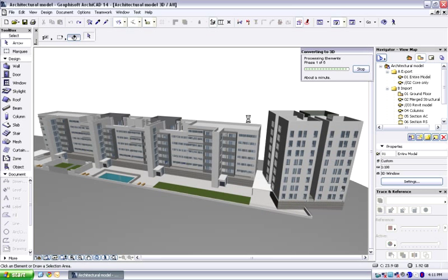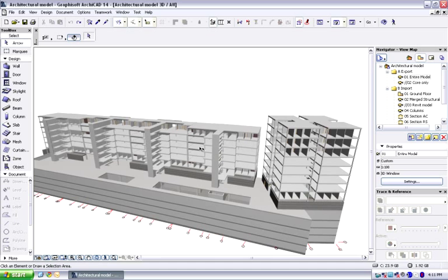This will hide all non-load-bearing layers of composite structures, such as insulation and mortar, and also hide all the elements that are not classified as load-bearing. The filtered model will be displayed in seconds on the screen. Now, only the building skeleton is visible, so only the load-bearing elements are displayed. The model looks fine at first sight.